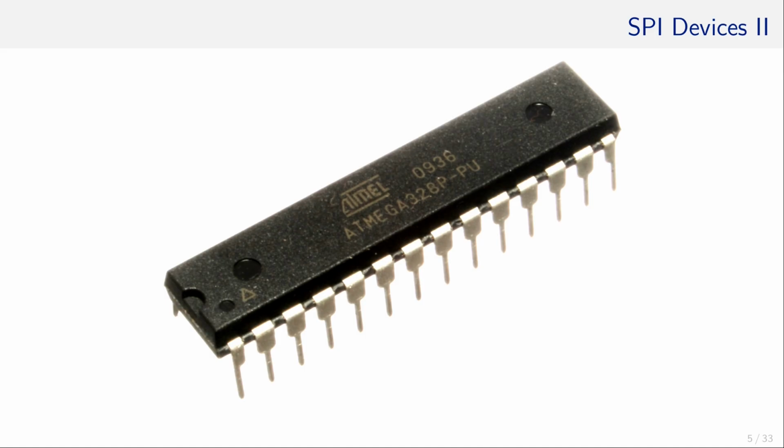The SPI also allows us to program the so-called fuses. Fuses are non-volatile configuration registers which cannot be written to just like that. They configure important settings such as the clock source, which is already required when it comes to the uploading of our program.